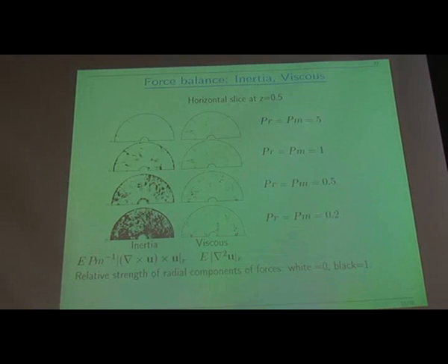You can hardly see it, it gets a bit lost there. There is actually a very, very thin layer there, which, if you look at it more carefully, is significant. The Ekman layer is of order E to the 1/2 thickness, and these are rather small Ekman numbers, so this layer is very thin.